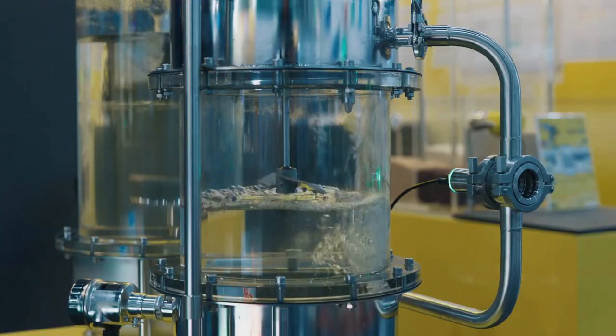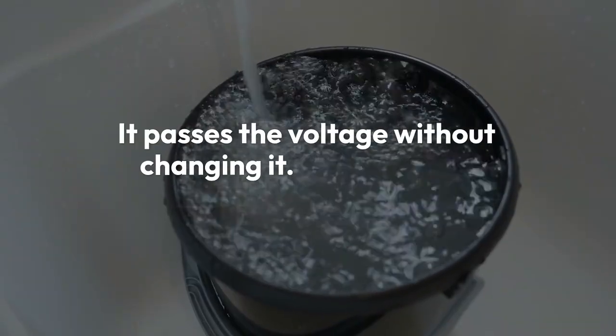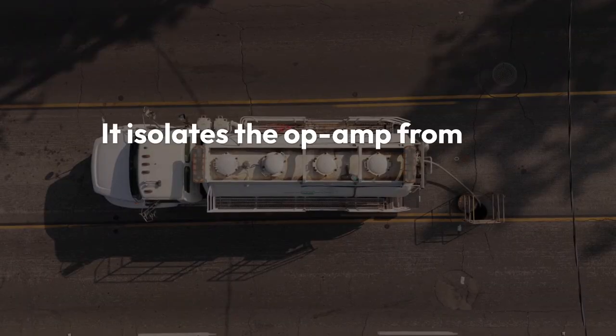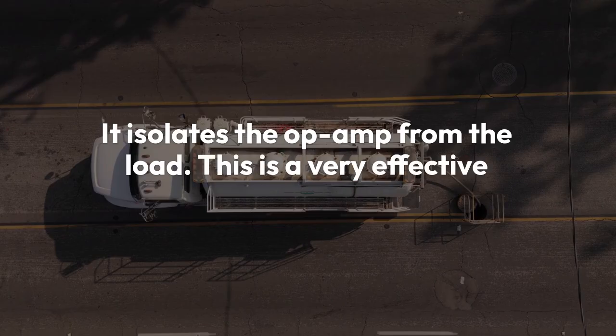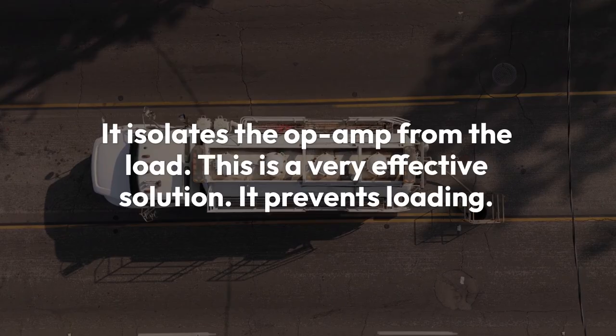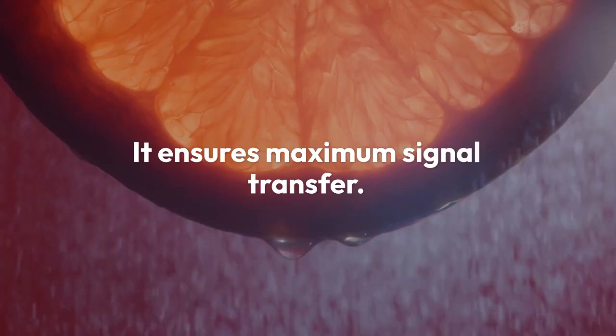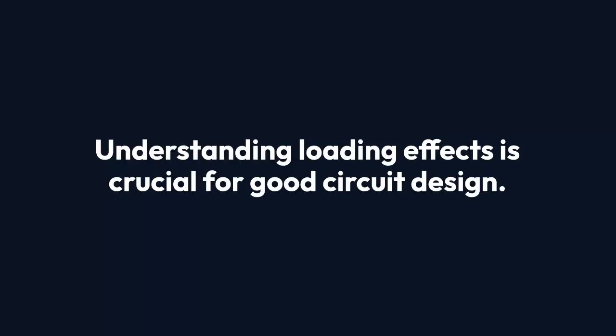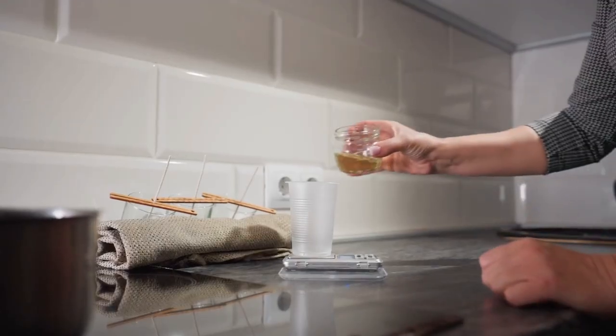A buffer has very high input impedance. It has very low output impedance. It passes the voltage without changing it. It acts like an impedance transformer. It isolates the op-amp from the load. This is a very effective solution. It prevents loading. It ensures maximum signal transfer. Understanding loading effects is crucial for good circuit design. It helps you get the performance you expect.